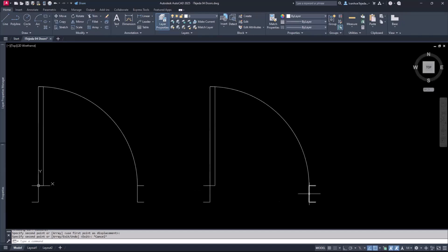First of all, it's 3 feet, which means that I need to take this jamb and move it over by 6 inches. So I have it selected. I type M, enter. And this time I am going to turn ortho on. And I'll click at this point here. It doesn't matter where you click. Yeah, I can even click in the middle of the screen here, but I'll use this as a point to start off. And I want to take it over to the right, so I'm indicating the direction, and then I type in 6 and enter. So that is now 3 feet.